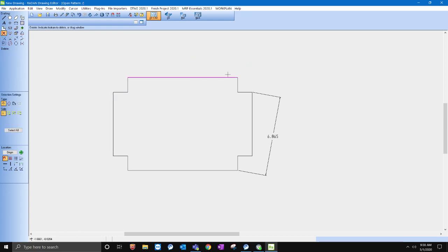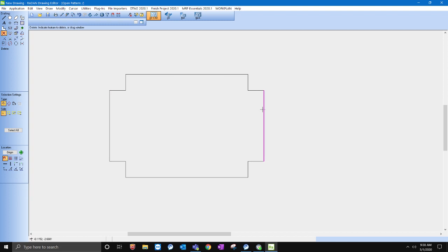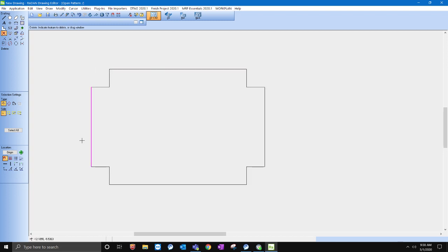There's some other stuff I'd like to do, right? So maybe I want to grab a notch and put some notch and corner details in it. So let's grab this corner notch here, and I'm going to go 1.25 on the width, and I'm going to go 1.25 on the depth, and I'm going to just select the corner, whoops, and select the corner, and I messed up my dimensions, but I'm just going to get rid of those. So there's my part here now, right?